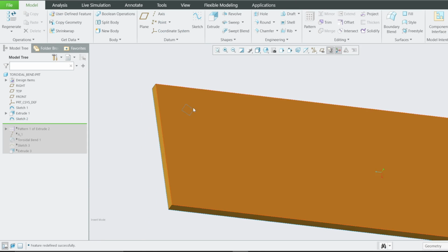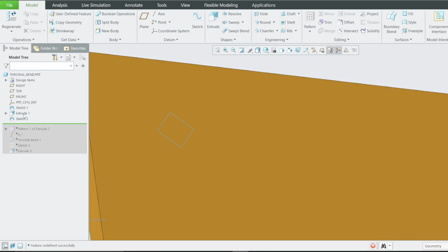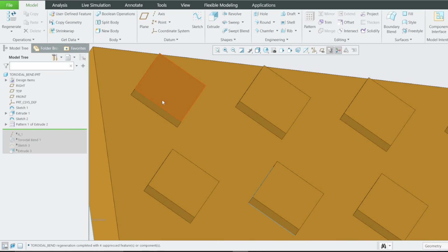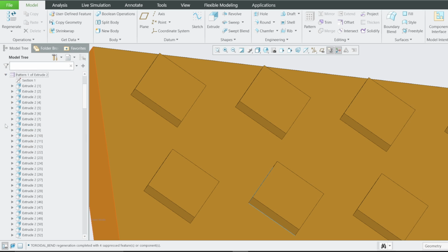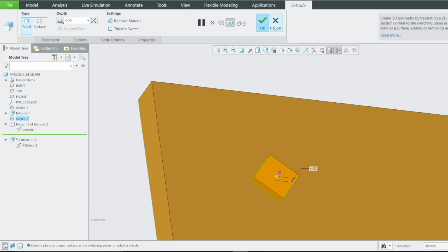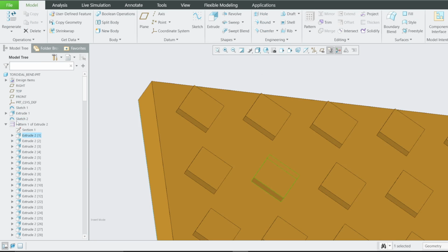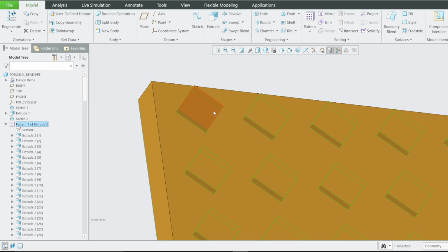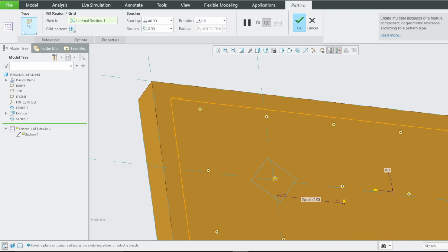You can extrude it. I have done an extrusion of that profile here. Let me see the extrusion here. Just extrude by about 4 or 5. Then after that, what I did is I patterned this extrude onto this face. Therefore, I used what we call fill pattern.